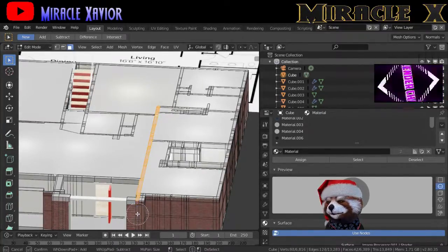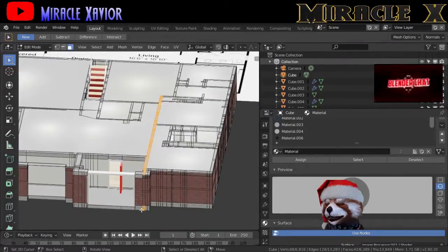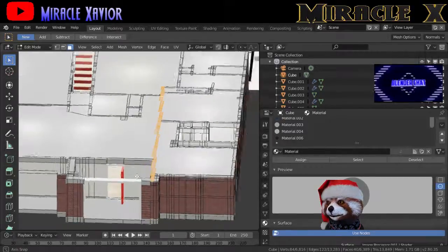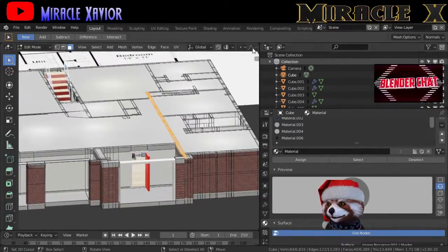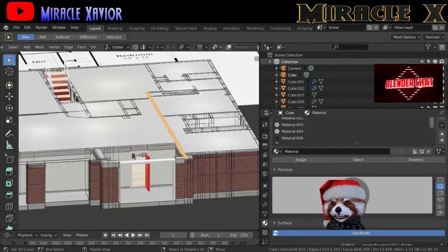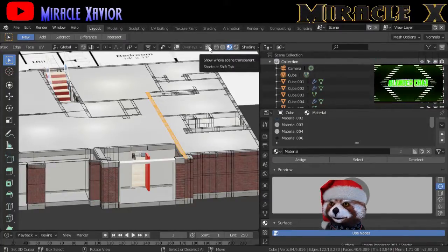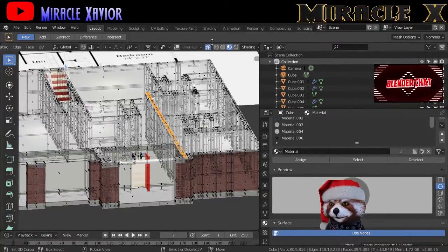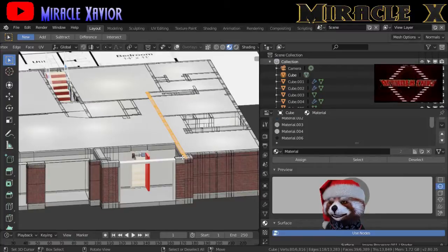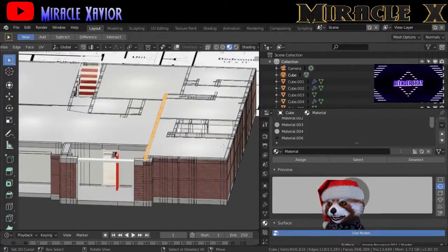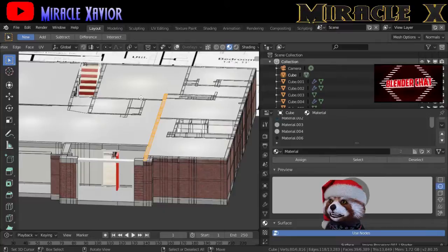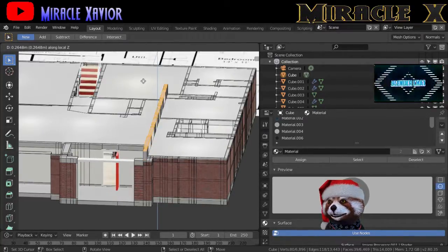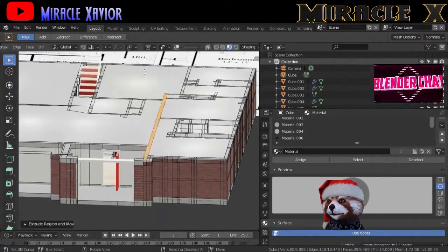And then you have a middle mouse scroll wheel, you can just click on it and you'll deselect the parts that you don't want. And then when you click for this right here, for the transparency, you can be able to erase the stuff that's wedged in. And all you have to do is just select all the parts, and then press E to extrude, press Z if it can go up, and you can build up your wall.